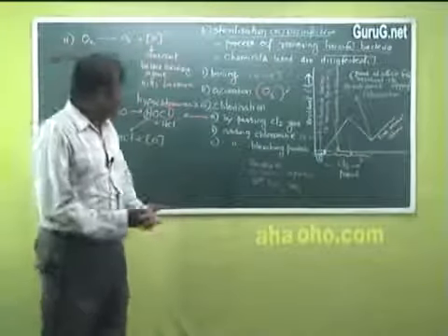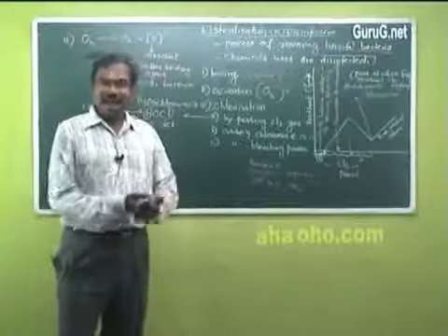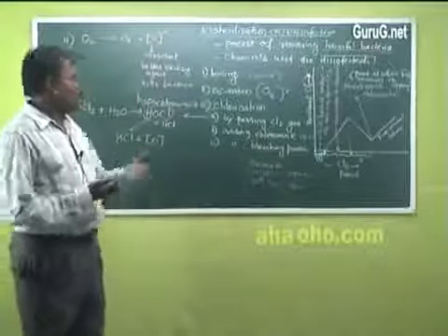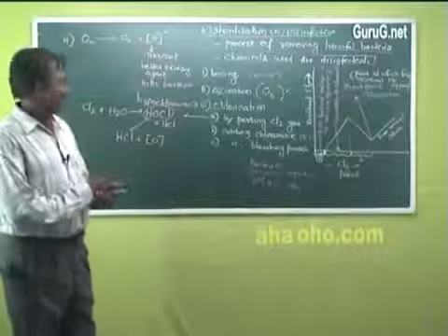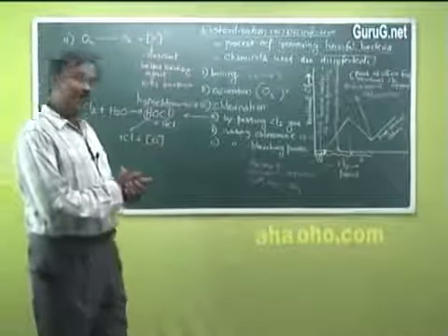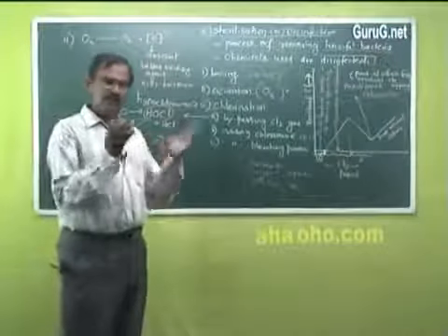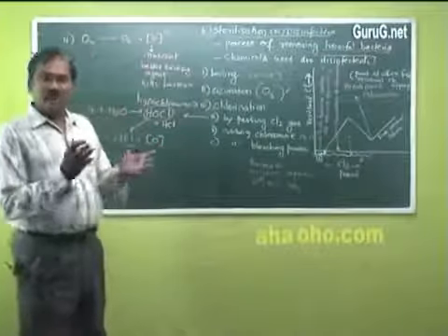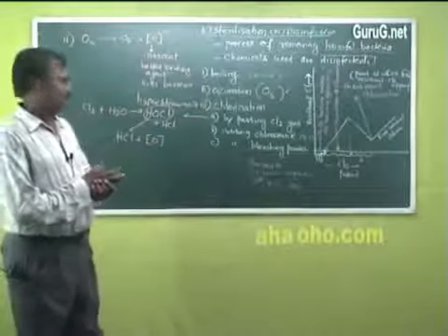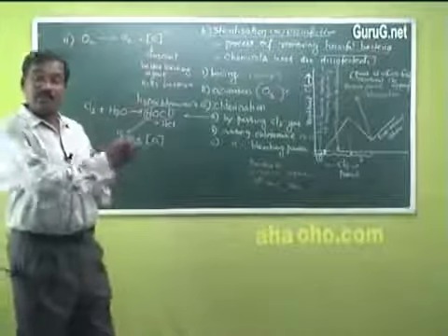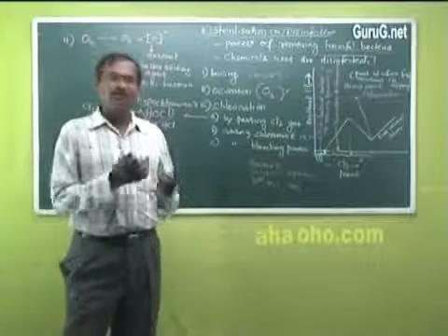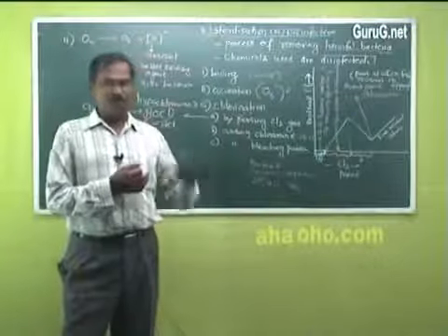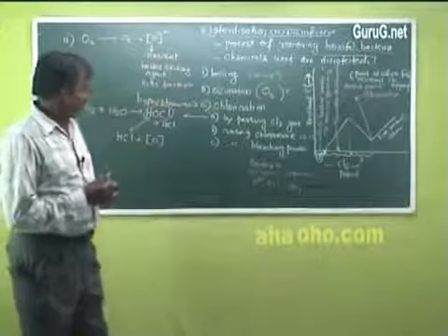But we have a problem with this chlorine handling. Since it is a gas, passing chlorine is not that good a technique. And another problem, if the water is having some hydrocarbons, then this chlorine will combine with such hydrocarbons, forming compounds like chloroform, which is not good for health.